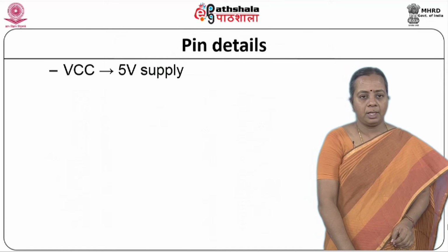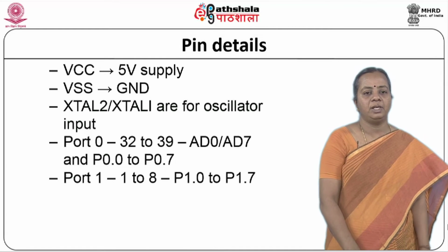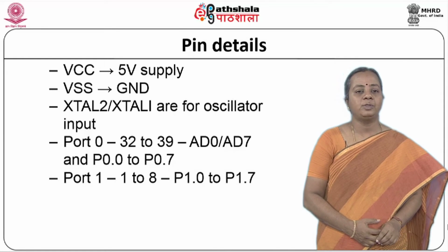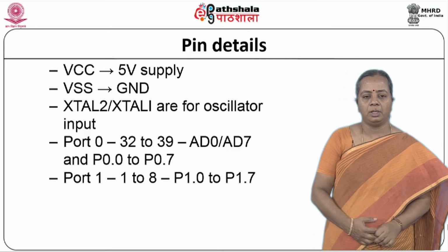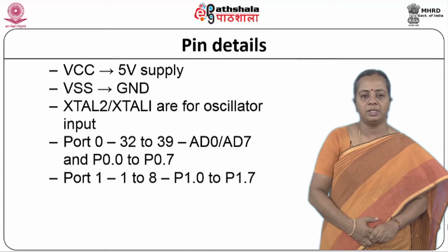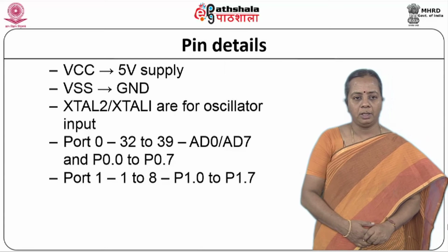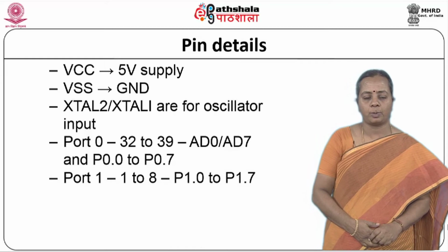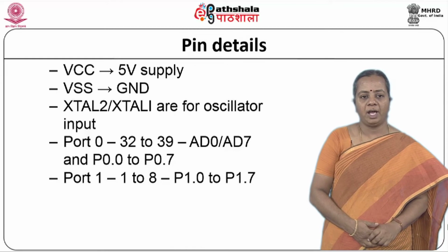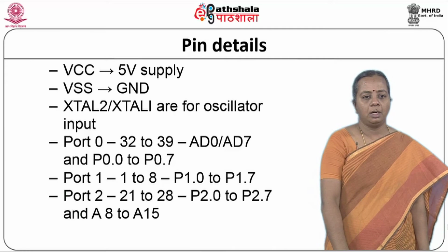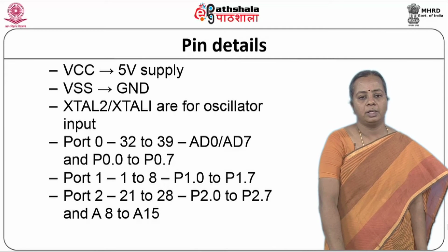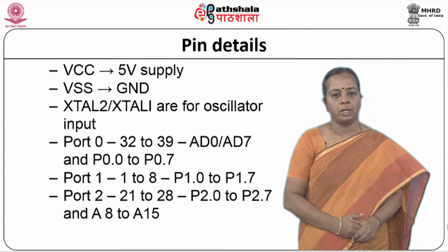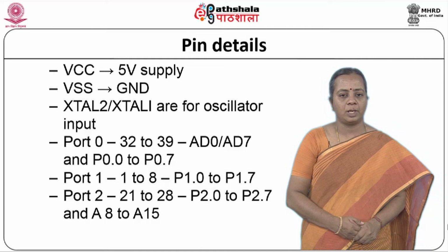When you are looking at the pins, we have VCC, to which we have to give a 5 volt supply, and VSS is the ground pin. We have 2 crystal oscillator pins, XTAL1 and XTAL2, which provide the clock inside to your microcontroller. We have port 0 and port 1, where port 0 uses pins 32 to 39, and this is a multiplexed port which you can use for address as well as data.